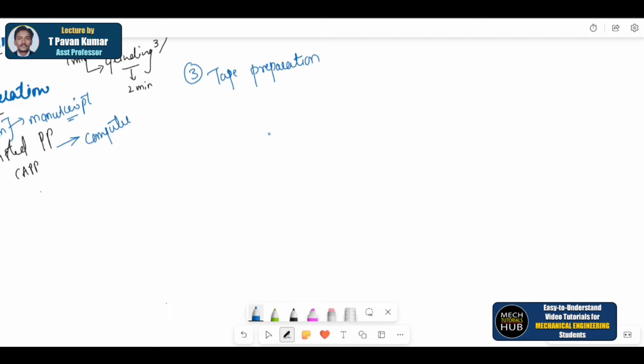Now that is prepared, as I said in the previous lecture, on a 1-inch punched tape. Okay, a punched tape is prepared from the part program. With the help of a part program, a punched tape is prepared by a programmer in the form of an NC process plan. In manual part programming, the punch tape is directly prepared from the part program manuscript only.